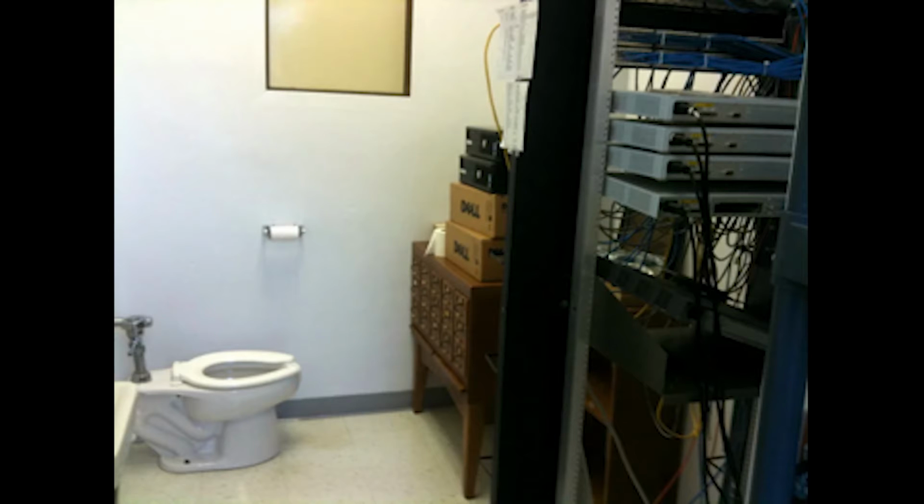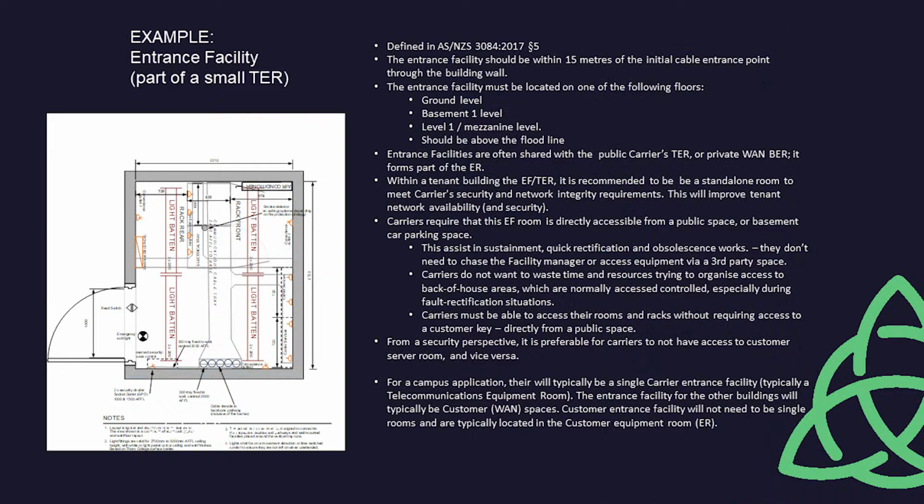In a single-tenant building environment, it is typical to have the consolidation of spaces, depending on the floor size, which differs slightly to the slide, to have the base building operational technology and the corporate network equipment room functions located in a single room. If the floor plate dictates a dedicated telecommunications room, the base building OT telecommunications room and the corporate network telecommunications room are typically located in a single room. This reduces space, facility running costs, and makes security management simpler.